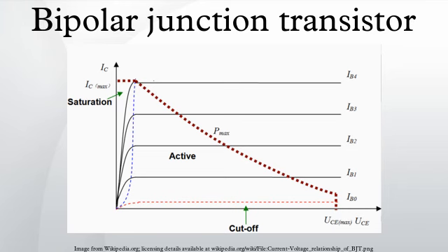It should also be noted that the h-parameter model is shown as suited to low-frequency, small-signal analysis. For high-frequency analysis, the inter-electrode capacitances that are important at high frequencies must be added.